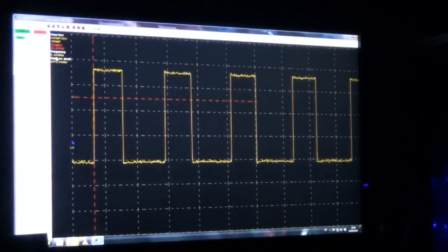And now I'm going to show you that with the oscilloscope. Okay, I am using my computer as an oscilloscope with a crap USB oscilloscope that I have around. Sorry, because I don't have a digital storage oscilloscope here. So as you can see, if I change the potentiometer, I'm changing the control voltage, and because of that I'm changing the duty cycle of this signal. So let's try.